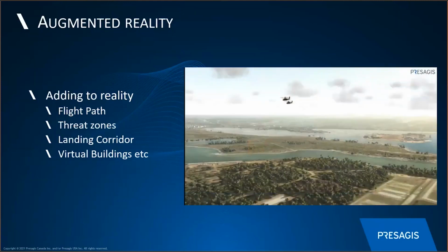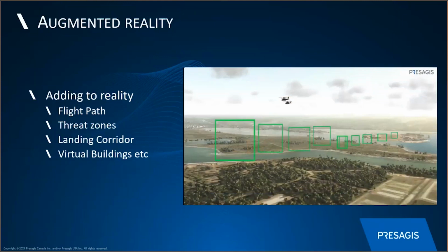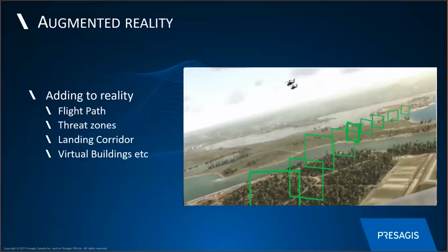And so when we're talking about advanced vision and doing this kind of tracking and positional information, an interesting topic is landing corridors, where we begin to highlight a path that a pilot needs to fly in, so that we can reduce the cognitive burden of the pilot by letting them know that if they want to reach this certain position, they just need to fly through this highlighted region. And as the pilot moves around or moves his head, the actual highlighted landing corridor will move around and follow where the pilot is looking so that it's accurately representing what the pilot needs to do.